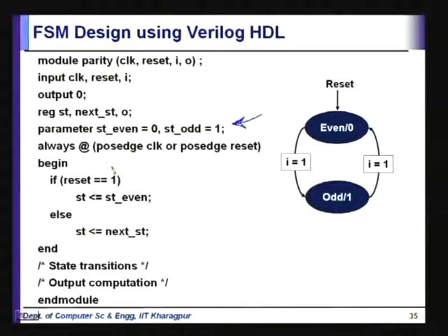So what does this tell you? When reset is high, then regardless of anything else, your next state is always ST even, and ST even is the 0 state.